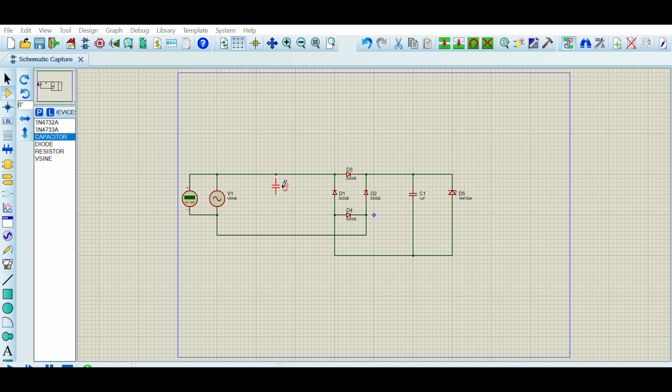So I'm just going to place a capacitor here, I'm gonna try and rotate that. Yeah, we're gonna have to get rid of the whole wire. Yeah, there we go. Then we introduce a resistor into the circuit right above the capacitor. Then we connect these two in parallel, positive to positive, negative to negative. Then we just join the two circuits from the AC and the bridge rectifier.